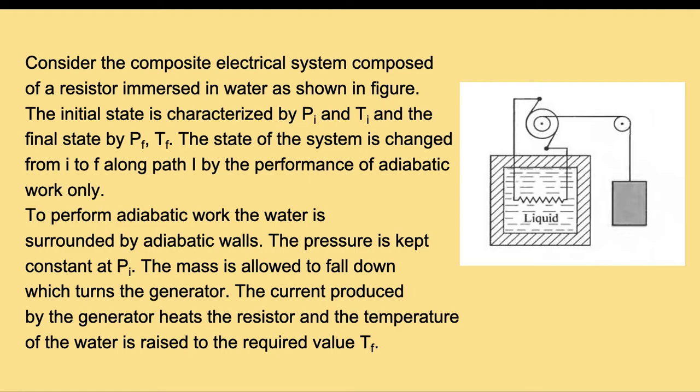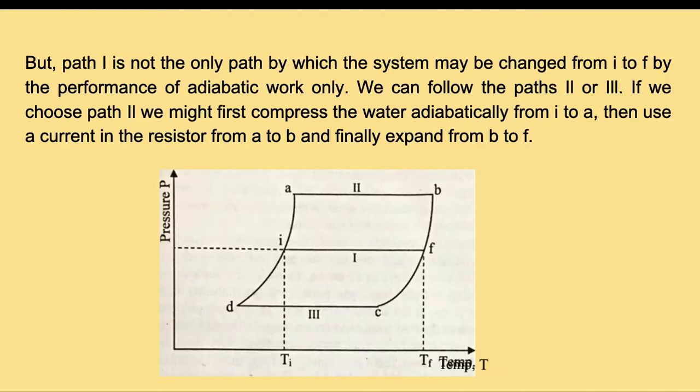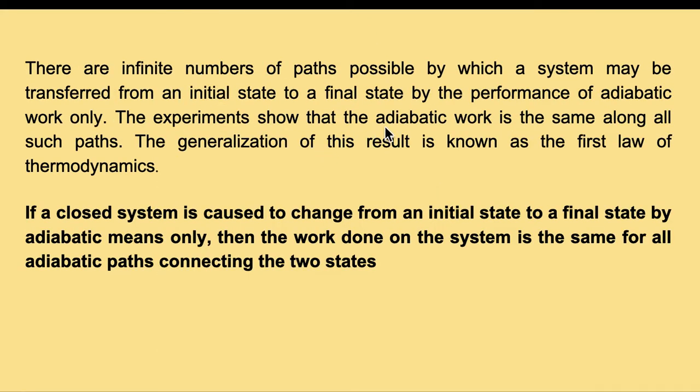The second way, you move this outside, so you can find the change in volume as well as pressure, that is PdV, and the compression. First you have compressing, then expanding, and you can find the work done. Also in that case you have the falling of the weight, and there also you can find the energy change. So by adding those three terms separately, you can find the total work done. That is possible. And it is found that in all such cases the adiabatic work done is the same.